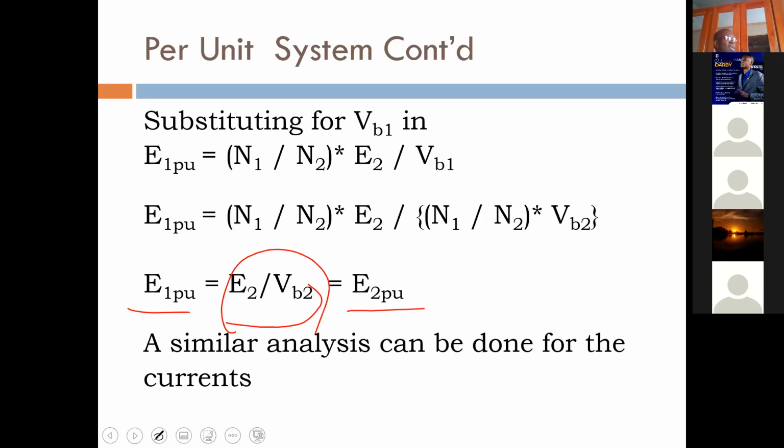And whilst we did not talk about it, in your machines, you would have done power factor correction and those things. You remember those things? In part of that discussion, I would imagine that you would have talked about the fact that the utility company will rate its equipment based on the MVA rating.